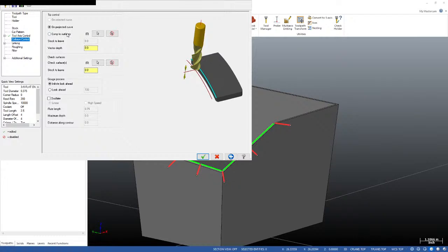Keep this in mind. For most 5-axis tool path cutting, you don't want to select a super complex group of surfaces as your cut pattern, because it just doesn't make any sense. You want to keep the cut pattern geometry as simple as possible.